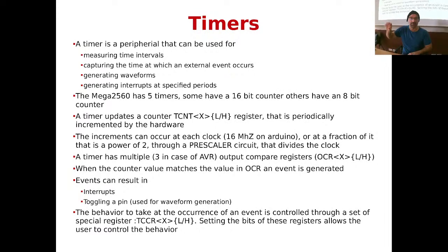It's like when you buy an alarm, you can configure it to do multiple things. The concept of a timer is trivial. You have a register that, based on some sort of event, is incremented or decremented each time the event occurs, right? And it's a register, which is a variable. You access it as if it was a variable. And by reading or writing this variable, you figure out how many events have passed, right? How many events happened. But this doesn't require the CPU to do anything. This is a device that runs on its own.